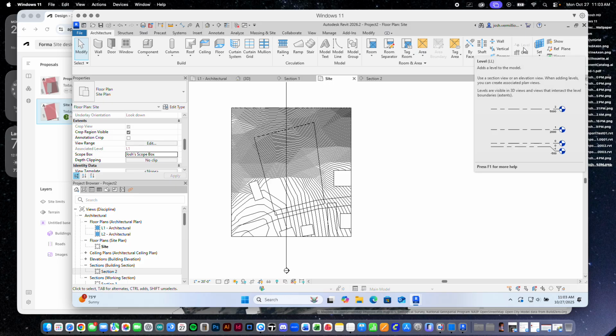Between grid and levels, I can actually construct a three-dimensional matrix of grid that becomes a sort of ordering system for how I modulate space, structure, and materials. So if you think about the grid, it's basically in plan XY, right? You're thinking about column grid potentially, where walls align, edges of floor slabs, etc. And when you look at it in section view, you see the levels. That's the sort of third dimension of grid.